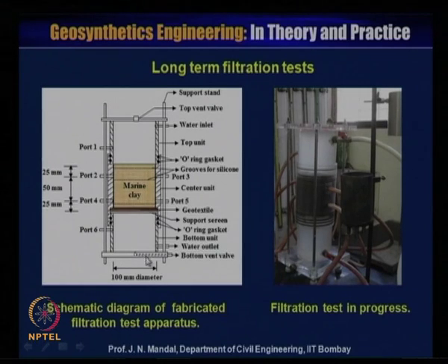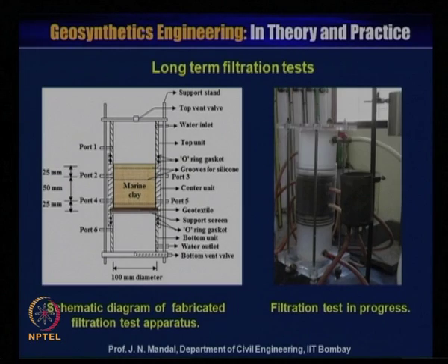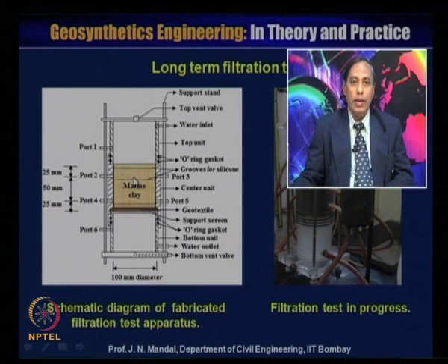I have already discussed this in detail in the earlier chapter, where I talked about the filtration, drainage and erosion control system. So, here is the geotextile material and this is the marine clay, like this. Here the filtration test is in progress and you can measure the water level, and then you can find out the filtration characteristics of the material.